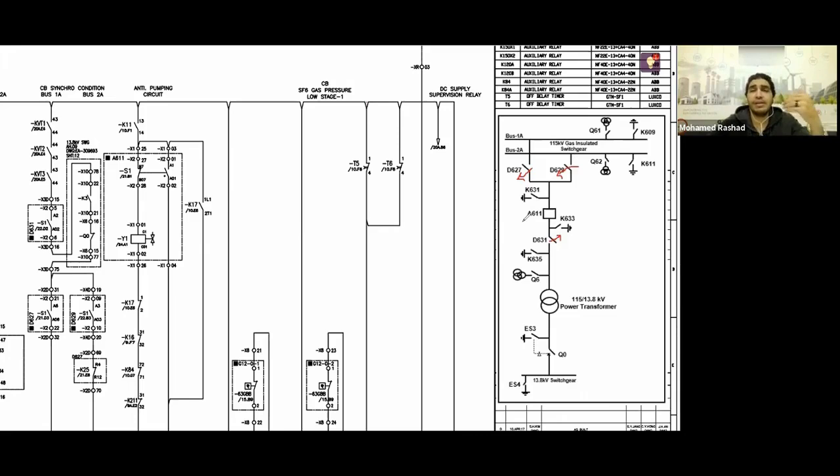What does the word mean? In essence, it means that before you take action here, in order to close my breaker, which is specifically referred to as such, I must ensure that the 3 disconnectors before and after it are indeed open. Great, nice. If you confirm that the 2 before it and the 1 after it, these 3 together are open, then I'm sure that this breaker is in the test position.